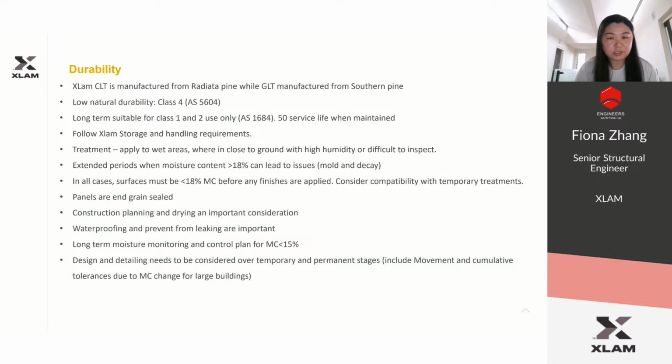Some of the large buildings in Europe or Canada are using a monitoring system embedded in the CLT panel for long-term monitoring. The design and detailing need to be considered over temporary and permanent stages, including movement and cumulative tolerance due to the moisture change for large buildings.